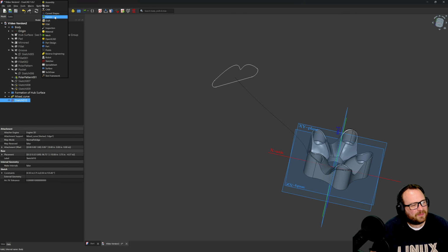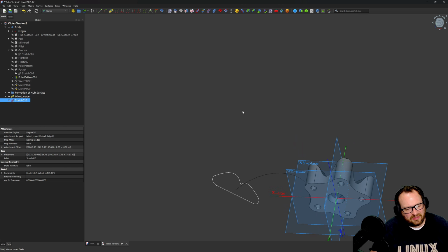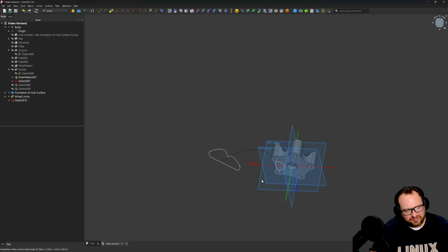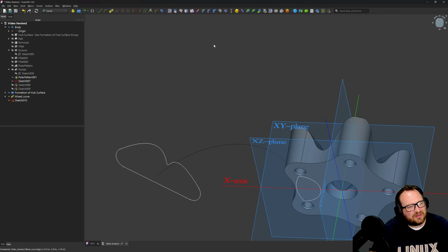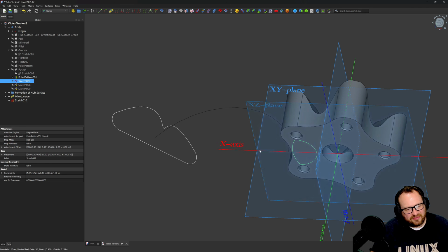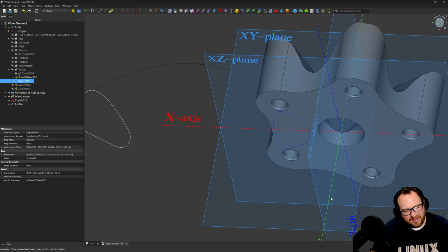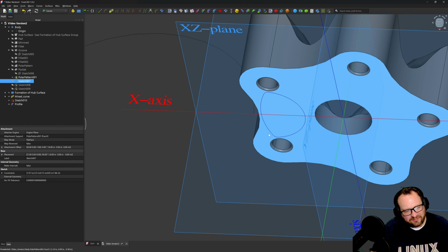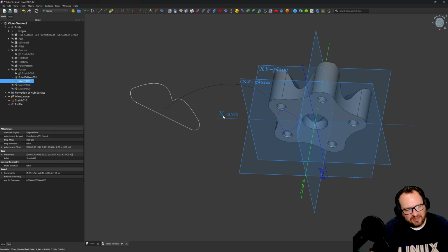We'll go to curves. And from curves, I'll show my sketch 007. And before I actually generate this, I want to use this pipe shell feature. And I need to have pipe shell profiles to do so. So I've got my sketches, and I can select, say, sketch 7 to begin with from the tree. So the whole thing is selected. And then I choose a pipe shell profile, and what happens is it doesn't just turn blue. It creates this fit spline, as you might know it, a spline that replaces the whole profile of everything so that there's no points. Everything's a lot more smooth.